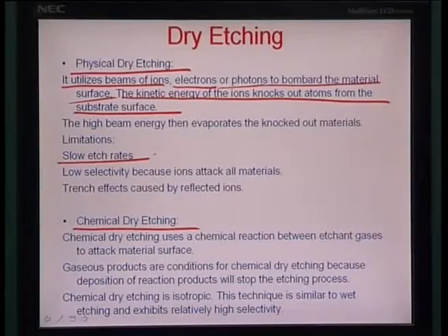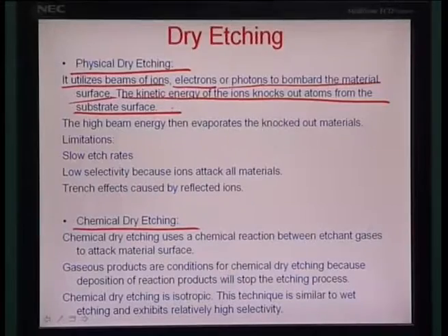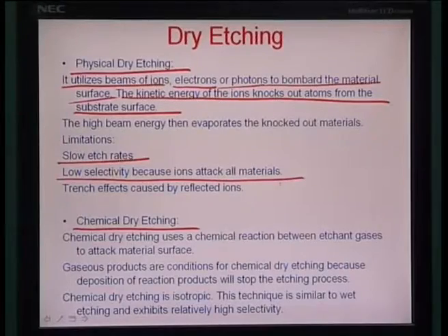Now, the major limitations are the slow etch rates, because you have to individually ensure that all the atoms and molecules are knocked off and vaporized completely from their solid bonds to a state where their mean distance goes at least 10 times more than the distance in the solid or liquid state. Low selectivity is also one of the major problems with this particular